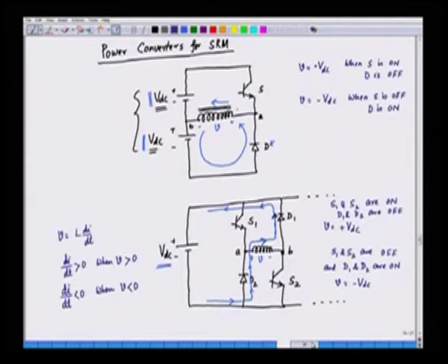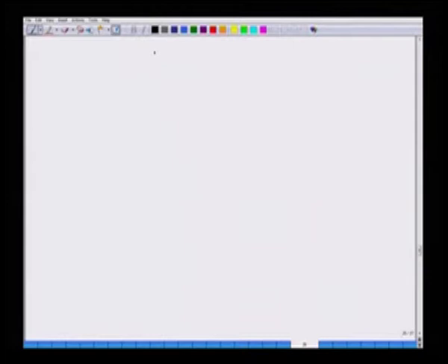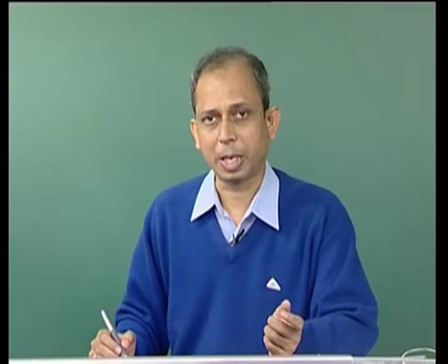We have the voltage here, that is the DC supply voltage, and we can have the transistor switch in this case, and then we have two windings per phase. This is one winding, maybe A, and this other winding maybe A prime. So, per phase we have two windings, and these two windings can be series connected.